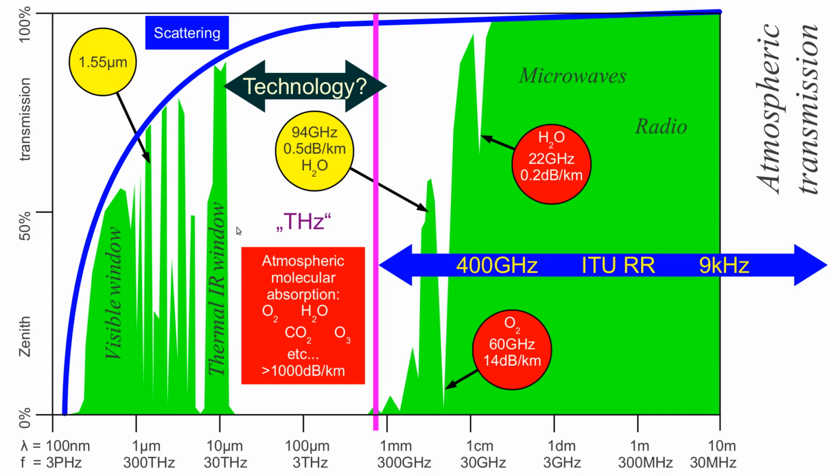We have a lack of components, a lack of active devices here, although there are millimeter wave lasers. There are detectors. Some transistors can go nowadays up to 1 terahertz, 3 terahertz. We still have Schottky diodes that can rectify 3 terahertz, but these components have very bad performance. Very difficult to use. Some thermal infrared detectors have to be cooled to cryogenic temperatures. That's again not something very practical. So it's not practical to be anywhere in between here.